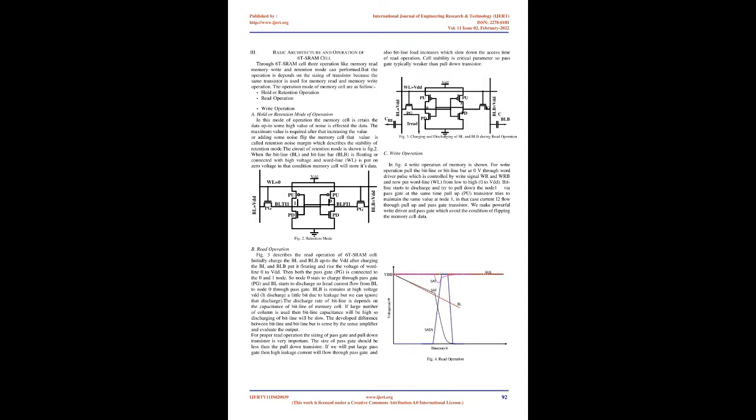In most cases the SRAM cell is made with less size to increase the density of the SoC and reduce the cost of the chip, because SRAM contains 20 to 30% of the area of the chip, which is significantly high.